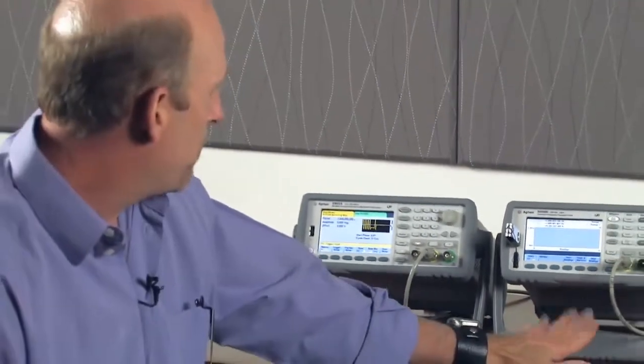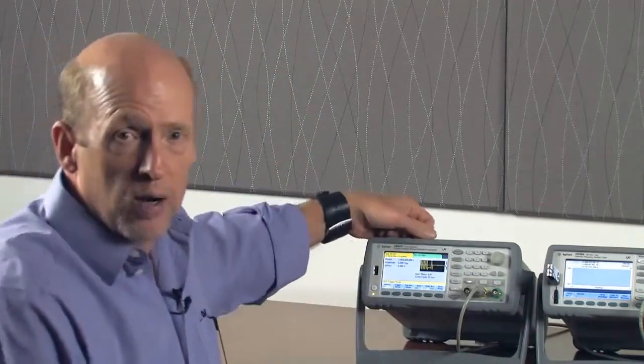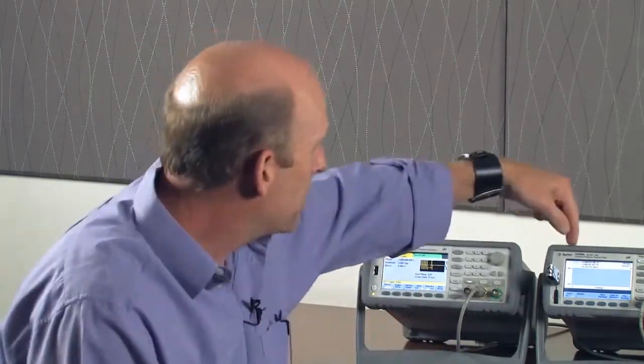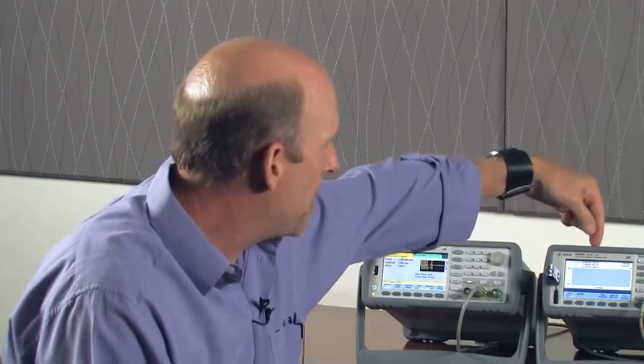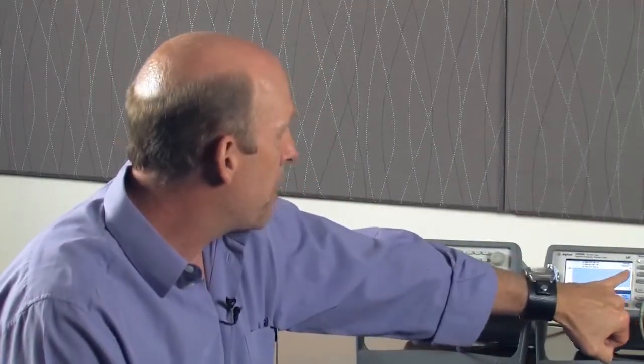What I had to account for was the fact that the first reading requires multiple cycles of the input signal in order to be produced. Once that first reading is taken, then in continuous mode, within one continuous gate open-close sequence, I'm able to take successive readings back to back on each of the 10 cycles. So although the function generator output 13 cycles, the first 3 cycles were required for the first reading, and I was then able to pick up consecutively the remaining 10 cycles, as indicated by my reading count shown on the display.